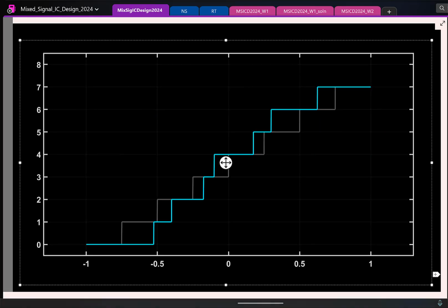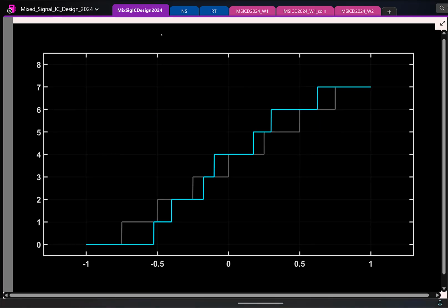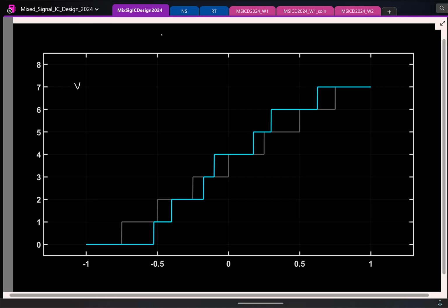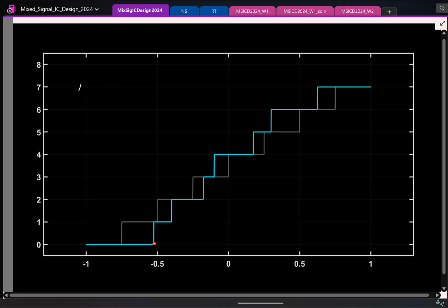So in practice, you will have everything like this. The standard way is you first find the offset, remove it, find the gain error, and then use delta average. So you take MATLAB or anything, take all these points, and try to fit a straight line like this.